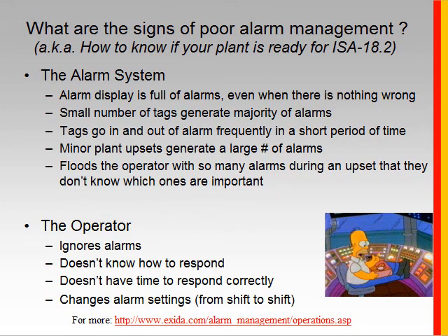We'll also look at the operator's performance. Does the operator ignore alarms or miss alarms? Are there some where he really doesn't know how to respond or what to do? Or maybe there's not enough time for them to respond correctly. And one of the other telltale signs of issues related to alarm management is if the operators are allowed to change the limits or the settings from shift to shift. Are they allowed to change it to what they want? Enable or disable alarms themselves or change the limits without authorization.